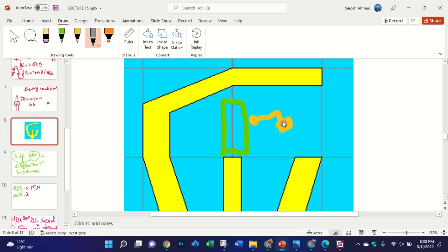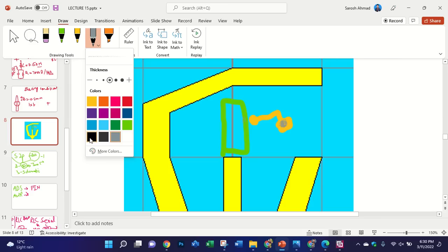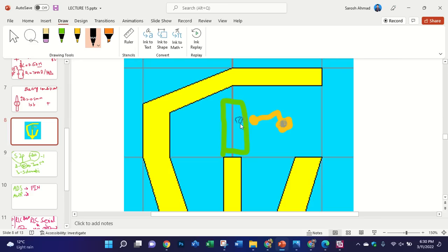At this point, sorry, let me change the color. At this point and this point, they are doing proper biasing or connecting the diodes. And wherever they want to use diodes, they create L-shaped stubs like this to achieve the circular pattern of the antenna.